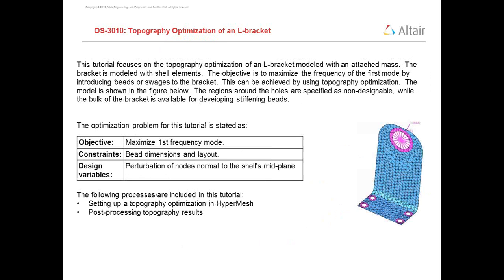This tutorial focuses on topography optimization of L bracket modeled with an attached mesh. The bracket is modeled with shell mesh. The objective is to maximize the frequency of the first mode by introducing beads or swedges to the bracket. This can be achieved by using topography optimization. The model is shown in the figure below.